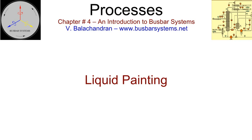Epoxy paint can be made of a two-part system that is mixed just before the application. Though air-drying paints are available, they can never match the quality that is obtained from oven-baked. Adhesion, bonding, and cross-linking are far superior in an oven-baked surface than on an air-dried surface. Liquid paints can also be applied by brush and rollers for objects that are large and require a heavier coat, such as in the case of outdoor structure steel supports. In an extremely corrosive atmosphere, liquid paint is applied by brush over the galvanized steel structure to provide additional protection.